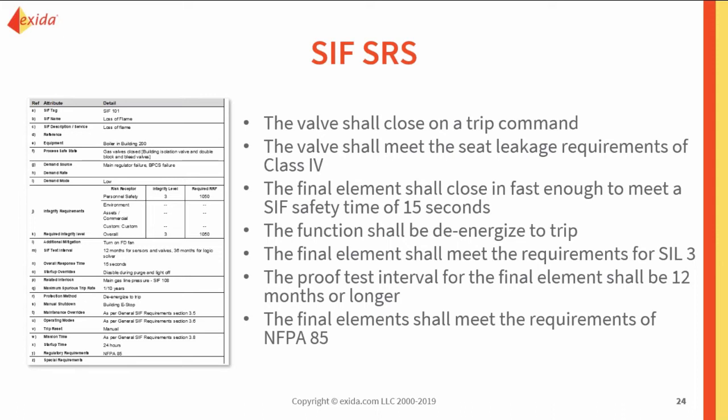The valve needs to have a tight shutoff, or a minimum leakage requirement, of Class 4 leakage. It needs to do the final element, or that valve needs to close fast enough that the SIF functional safety time is 15 seconds. So it's not just the valve closes in 15 seconds. The whole safety loop needs to react and shut down within that safety time.